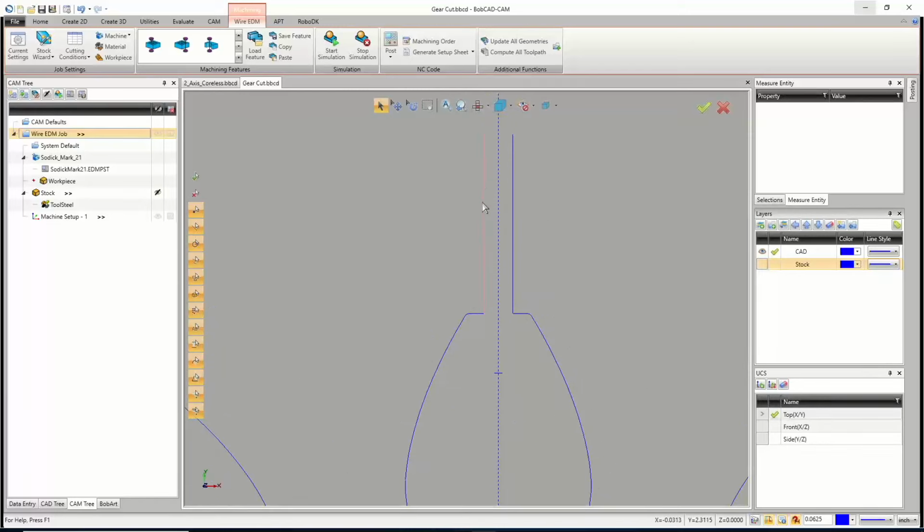If I look at this line, think about where the midpoint is. If I go to the bottom of the midpoint and hold shift and click, that's trying to send the chain up to any geometry that connects above that point. So it sends it in the opposite direction. When you're doing your check, find your midpoint. And if the geometry you want is below this, then we want to go above the midpoint.